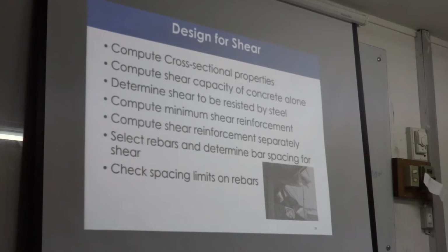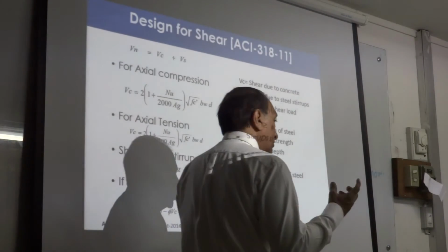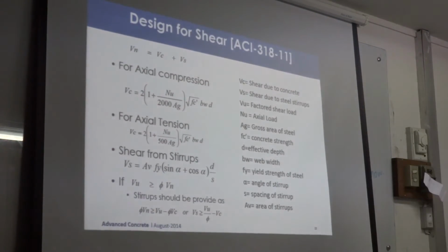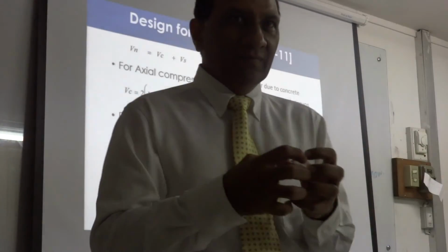But before we go to space stress analogy, let's put together the reinforcement that we need from our normal theories. Let's say we have a beam which is a T-section beam, and we have only axial load P, right? Where should the reinforcement go for the load? Suppose the load exceeds the concrete capacity in compression, or the load is in tension, in which case concrete has no tension capacity. Where should we provide the reinforcement?